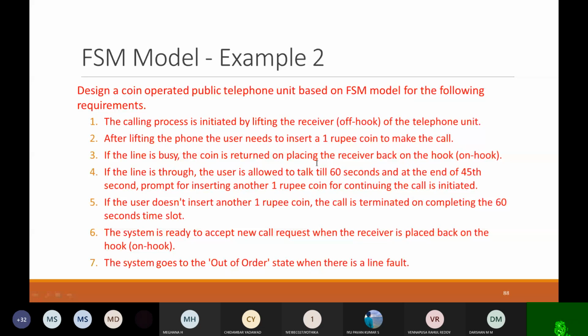Now I am in state B. From state B, I can go to A, I can go to C, I can go to D. Now what is this state B? Your first input, the coin, has been received. After receiving a coin, what do I have to do? I have to give an option for dispensing coffee, an option for dispensing tea, and an option to cancel the order, in which case I have to dispense the money. That is why I have taken 3 outputs here.